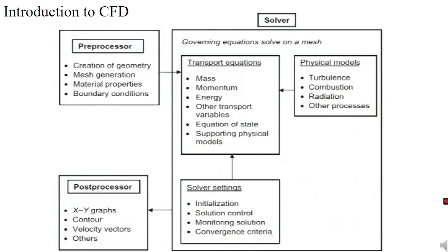In this case, what exactly is the converging criteria? Suppose I am saying 10 to the power minus 5, then it means the difference between the residual value of the previous iteration and the current iteration, if it goes below 10 to the power minus 5, then we can say the solution is converged and the simulation is completed.